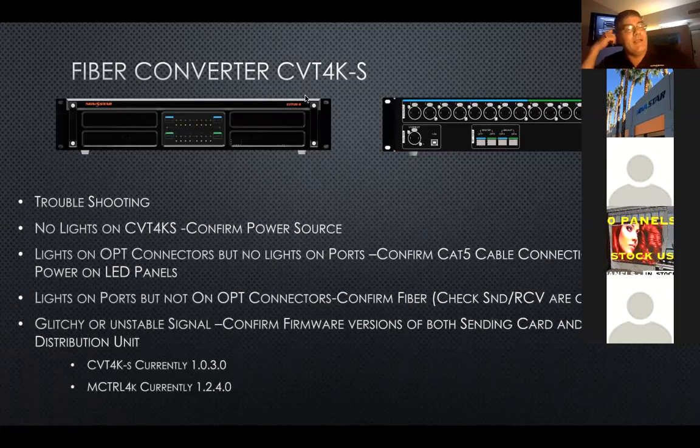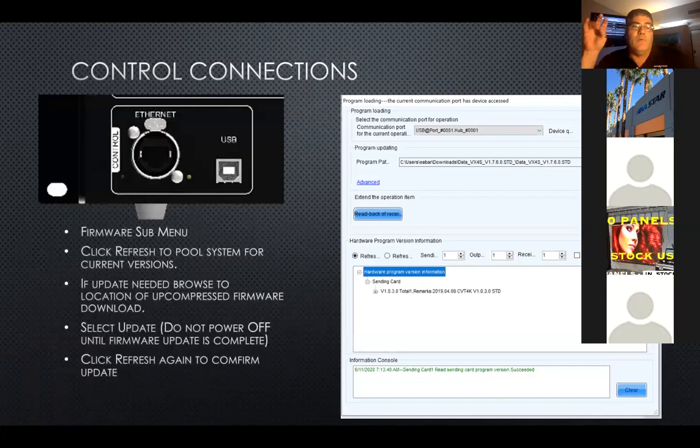Again, we're connecting through the USB A to B. If you log in to your NovaStar NovaLCT software, then you do your asynchronous login like you've always done. Then, with all 7 of your icons across the screen, you're going to type ADMIN, and that's